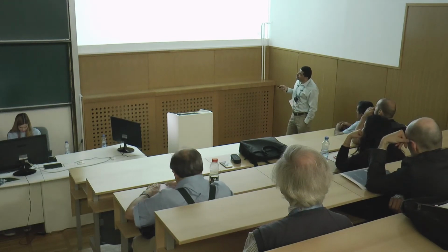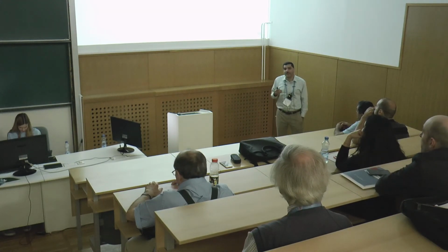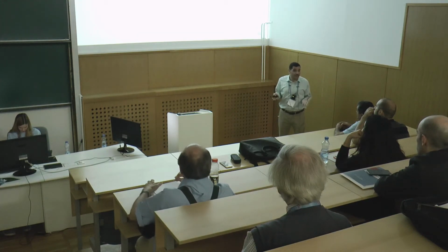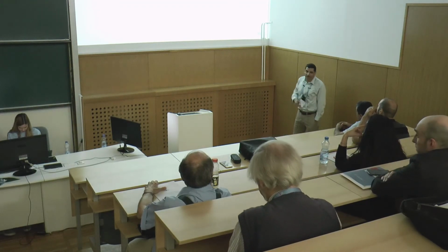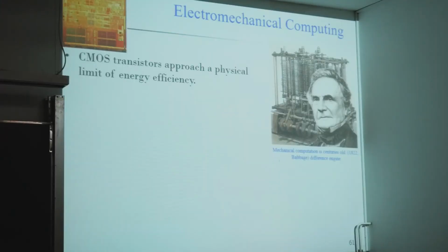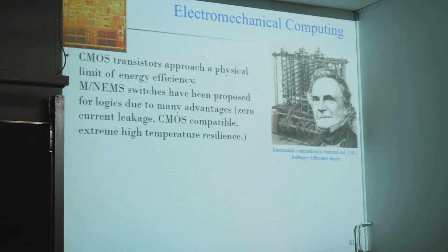So let's put it in this context. The current CMOS transistors, they have issues. They reach physical limits in terms of energy saving and in terms of how much you can put into one physical space. So people are seeking and searching for alternative logic units and alternative ways to do computation. And one of them is through MEMS. The idea is that unlike transistors, MEMS, when they are in the open circuit, don't leak energy. Whereas transistors, as many of us maybe know, leak current even in the off state. So there is a path maybe for energy conservation or energy consumption reduction.